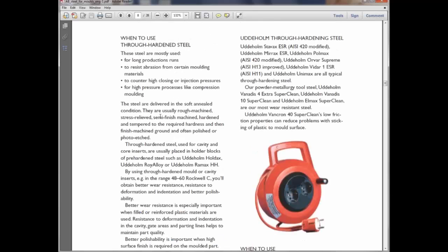So what happens when we start machining? We take the raw material and first of all we go for rough machining. In rough machining the depth of cut is high, like 0.5 mm, 0.6 mm, so that the process is completed in a short time.